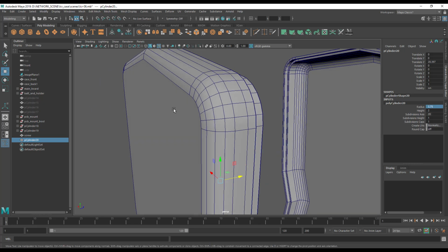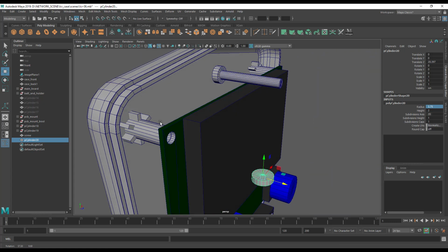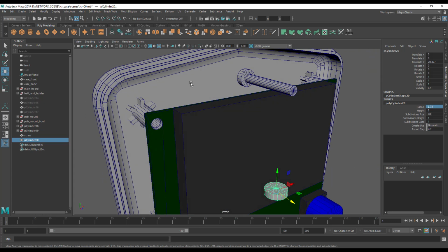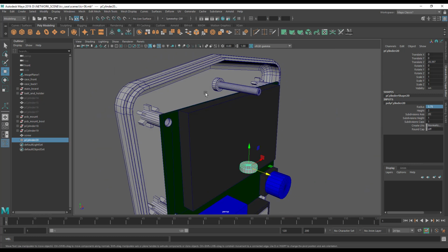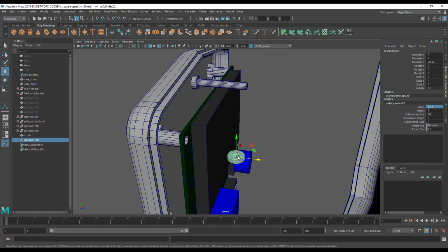Now the head will be screwed 2mm into the plastic through the case, and then we're going to have to see how far we want the head to protrude in here. Now for me that should be around 5mm. So the head will protrude a total of 7mm into the case. So I'm going to hit E to rotate this, and J.